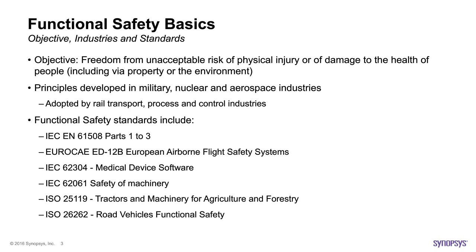The complexity of the SoCs that are feeding this market is growing very fast, and therefore, managing the safety for those is a key element that needs to be met. Safety means risk mitigation: operating errors, hardware failures, environmental changes that would create failures in the chips that will propagate to the system, and they need to be mitigated somehow.